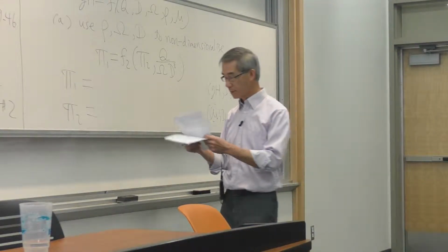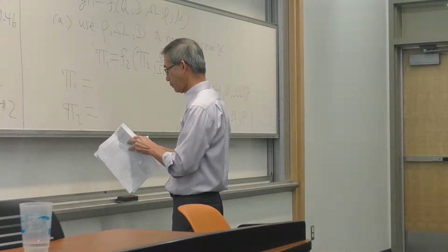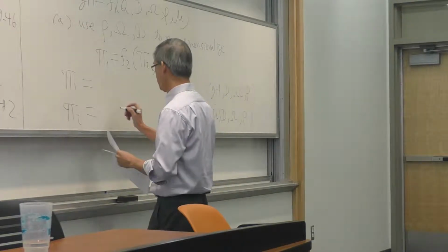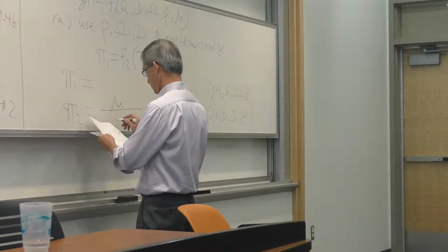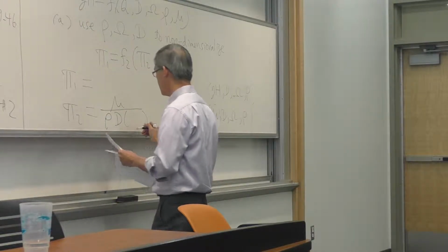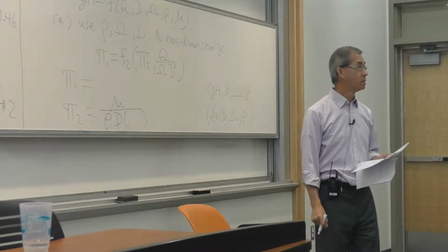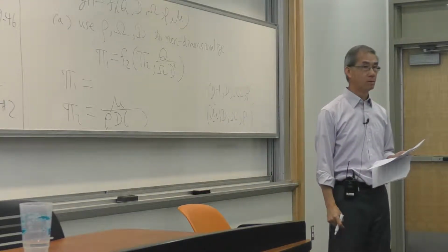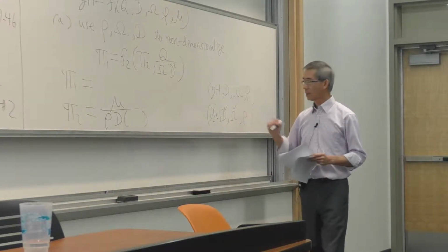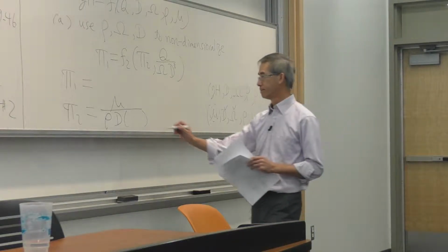So the Reynolds number is simply then the viscosity term mu, density, diameter, and the velocity. What's the velocity? What combination of diameter and omega, RPM, gives me velocity? The product.